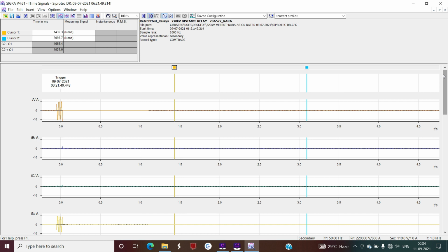Also, by using this same zone diagram, we can determine whether, before the inception of the fault, there was an import of power or an export of power. Also, what the fault resistance of the fault is, everything we can determine using the circle diagram.